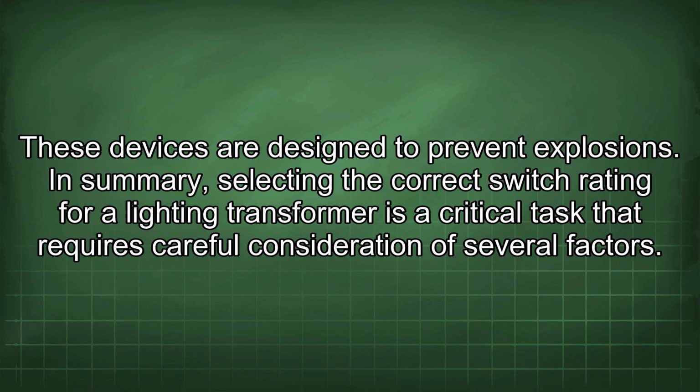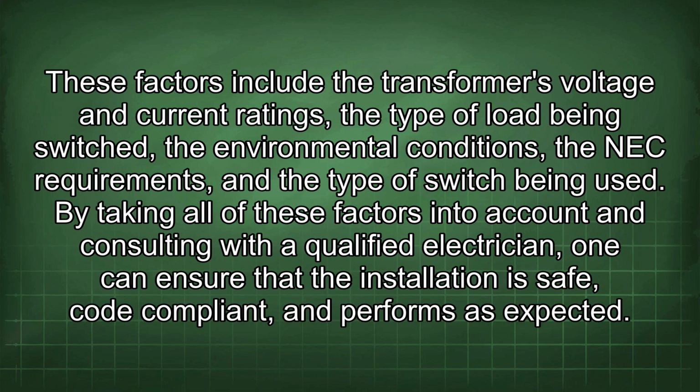In summary, selecting the correct switch rating for a lighting transformer is a critical task that requires careful consideration of several factors. These factors include the transformer's voltage and current ratings, the type of load being switched, the environmental conditions, the NEC requirements, and the type of switch being used. By taking all of these factors into account and consulting with a qualified electrician, one can ensure that the installation is safe, code compliant, and performs as expected.